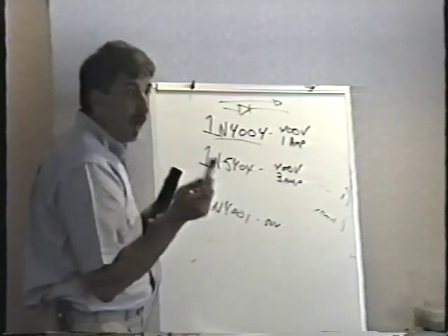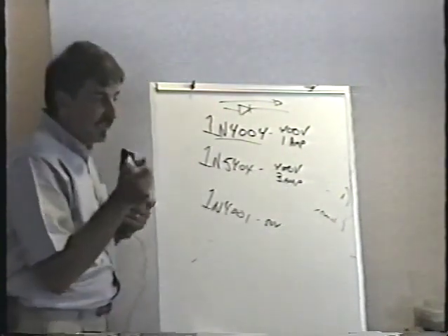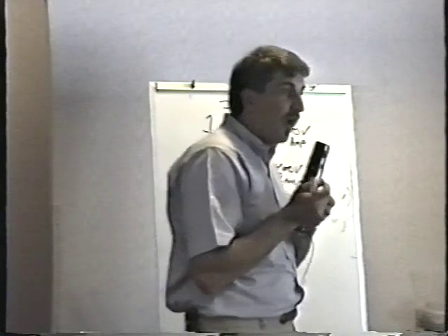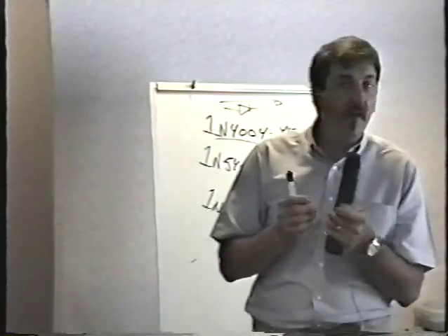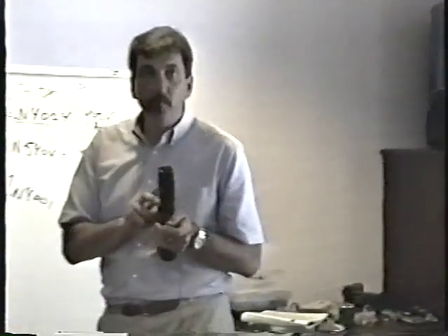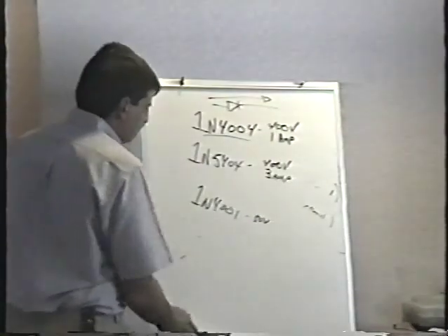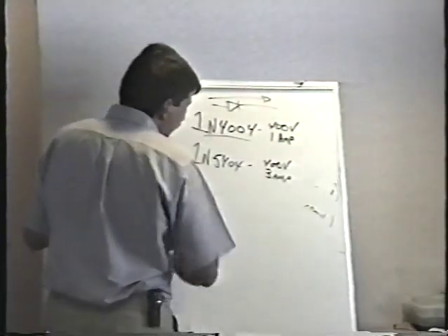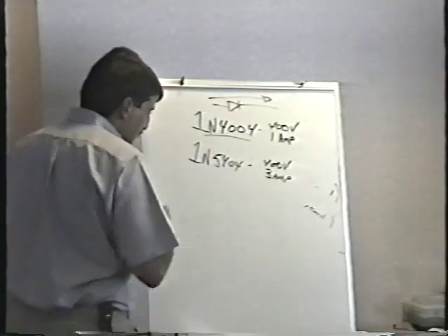Absolutely. Only problem, look at the size of the leads. You see how fat the wire leads are on the 3 amp diode, the 1N5404. The component leads are very fat, and you may not be able to get them in the hole. Rather than make a big hole in the board, if you ever have to do this, and I seriously doubt you will, here's what I do.